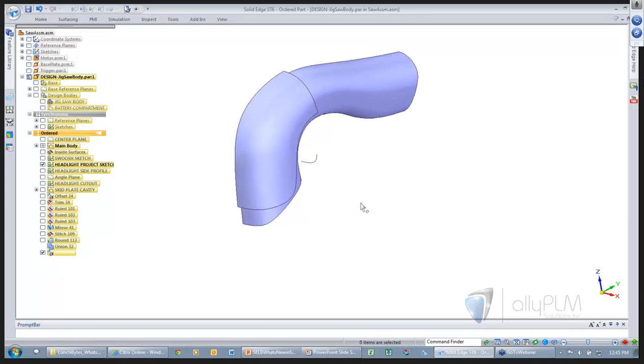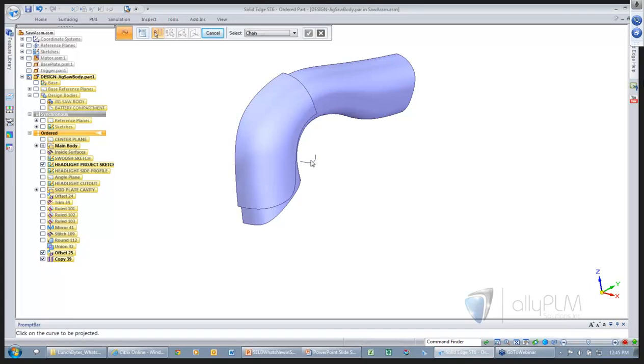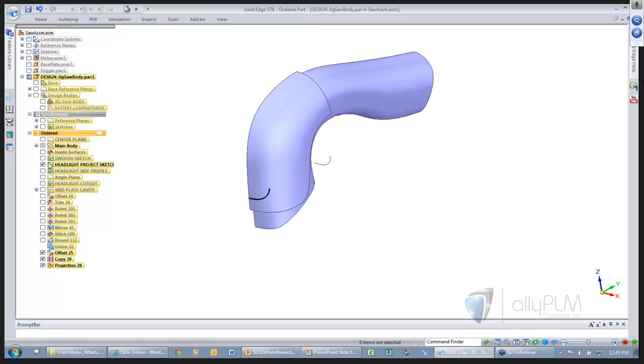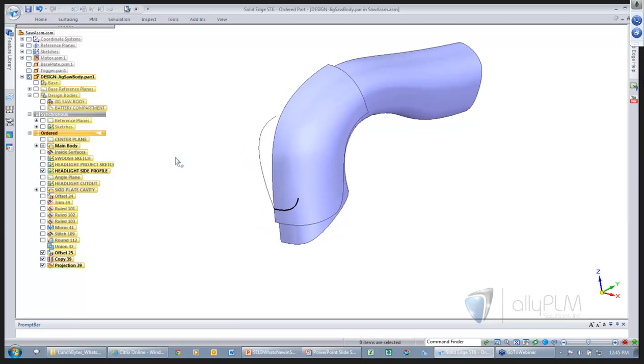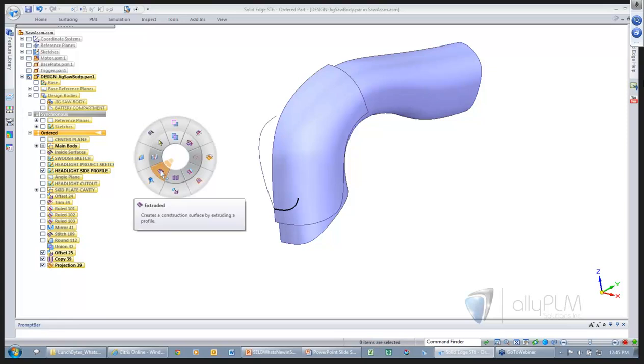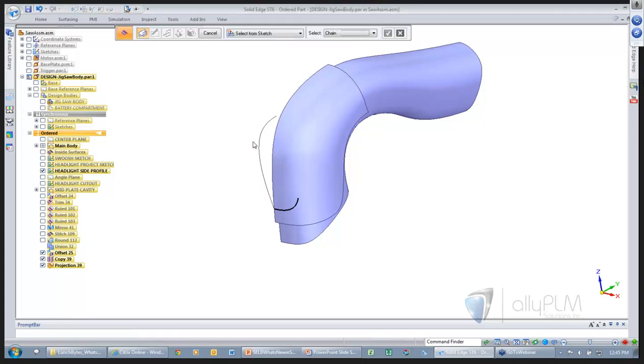And I have a sketch created that I just need to project forward to my offset surface. We've used project curve before. And I also have a sketch here for a profile. This is going to be kind of the front curve, if you will, of the shape of the profile. What I'm going to do is use an extruded surface command and extrude this out a certain width. It doesn't matter how much. And I'm going to call this a strip surface.